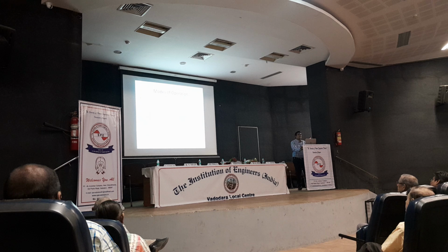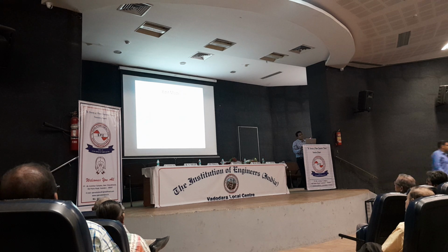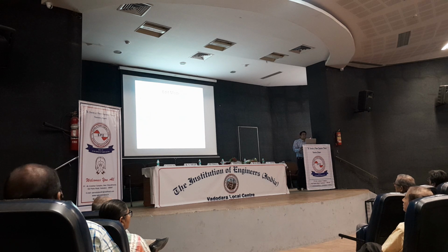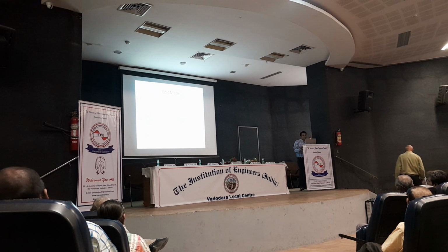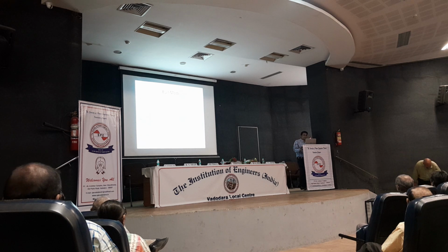So basically, by and large, this simulator PowerWorld will work in two different modes, edit mode and run mode. In edit mode, you can create new power flow cases and modify existing cases, and you can modify either graphically or via text displays. In run mode, as I have discussed, this many tasks and this many analyses can be done.